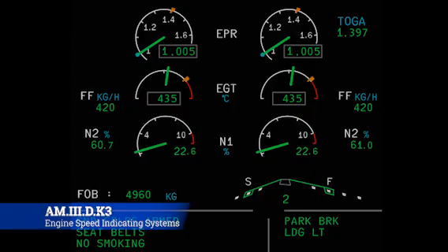EPR, your engine pressure ratio, is going to be looking at the air, not just the fan speed. Now, all of these give the pilot a pretty high level of fidelity on the health of those two engines and what they're doing, and different indications on either one of them will help inform, hey, look, this is what's going on with that engine.